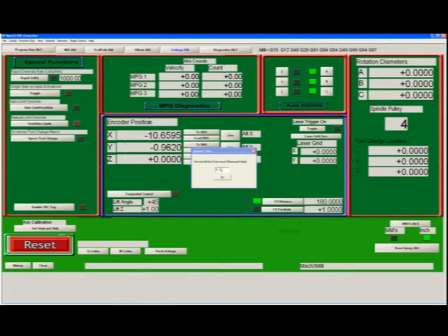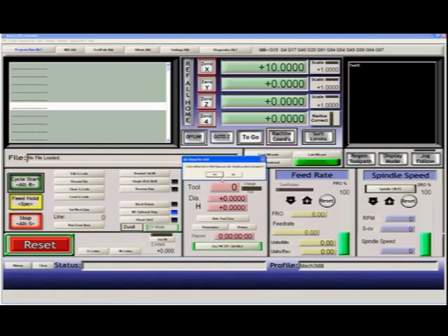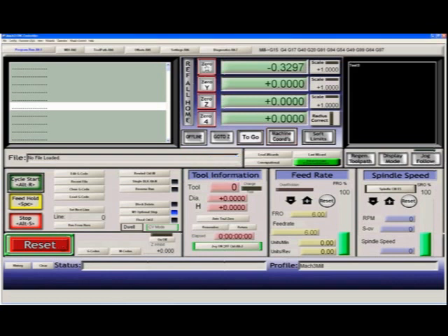If we now measure the system, your axis would have just moved from its position to a new position. You have to measure that movement. If we tell it that we actually moved 5 millimeters, it will now set the axis to 4,000 steps per unit, which will be accurate. We say yes, and the x-axis has now been calibrated. If we now zero the x-axis and jog a particular distance, you should be able to measure that, and it should have moved exactly 2.1877 in this case.